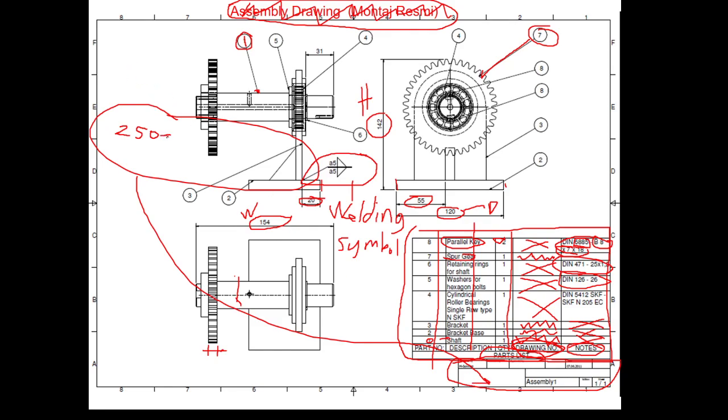Put a dash and then write 0. If in the assembly the number of components is less than 10, one zero. Greater than 10 in number but less than 100, two zeros. If the assembly consists of more than 100 components but less than 1000 components, then write one more 0, and so on. That is the drawing number for that assembly drawing. Write it into the box.